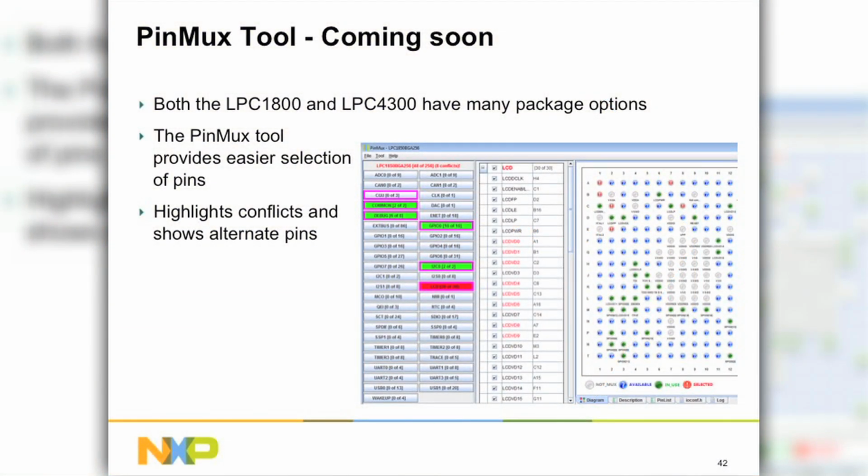Okay, so just a couple things to mention. A little known feature is you may have a 100-pin part, but we have a really extensive pin muxing, which means any one pin can be almost up to 8 different things. So usually on a 100-pin part, you have to choose a certain configuration. We make it really easy for you to say, let's say I want these peripherals. You can set up your matrix, your pin muxing, to determine which peripherals and use a smaller part. So basically, the pin muxing allows you to use a smaller part and get the things that you want in that peripheral.